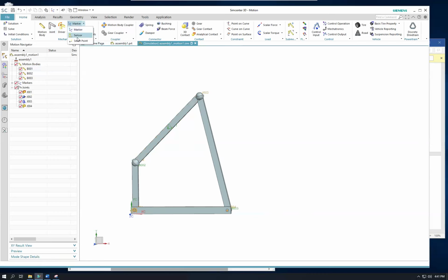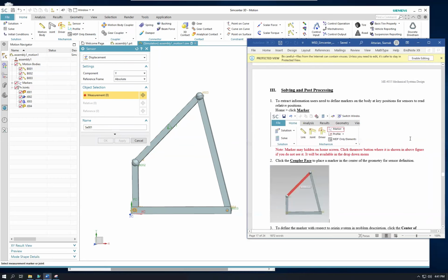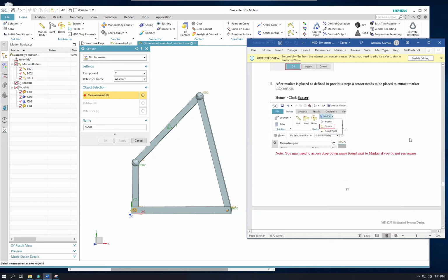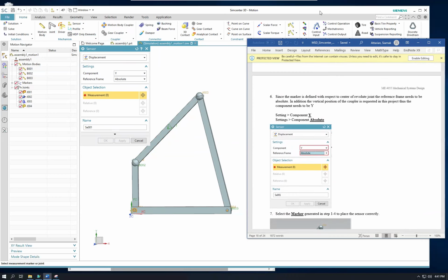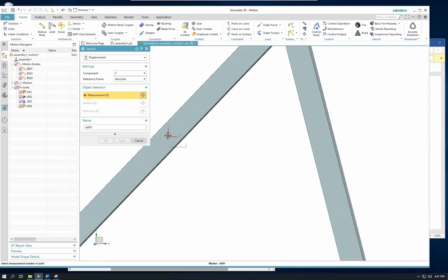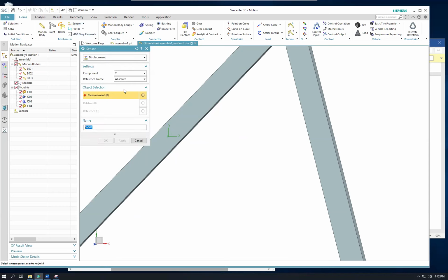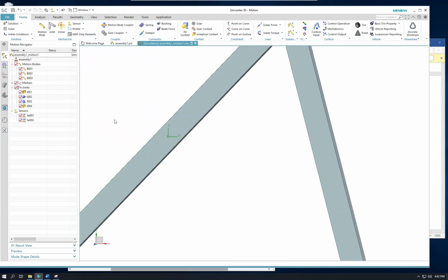And then after creating your marker, you have to create two sensors, one for keeping track of the displacement. So this is displacement in y direction, and the absolute value. Is it absolute or relative? Oh, it's absolute. Since that point was 0, 0, 0, both are the same. Doesn't matter. And select object as your object here. You have to select this marker. Okay. And you need another sensor. This time, velocity in y direction, absolute, and same marker. Okay. So now you have two sensors here.